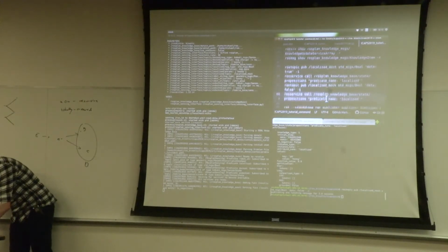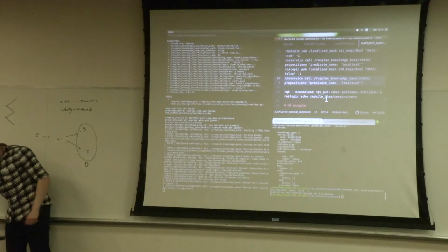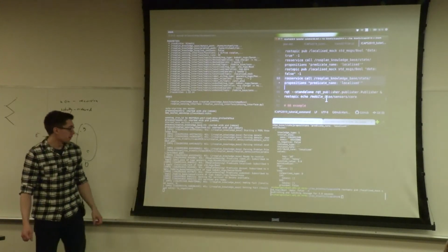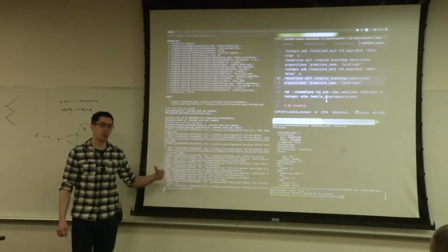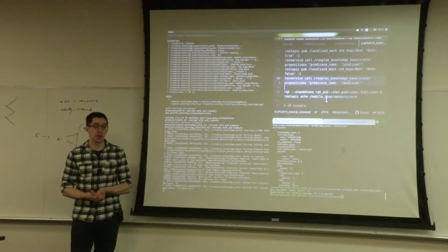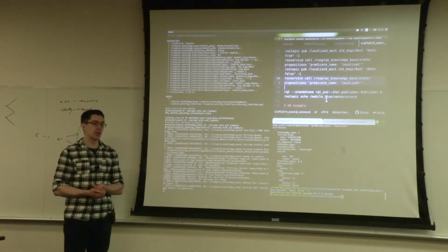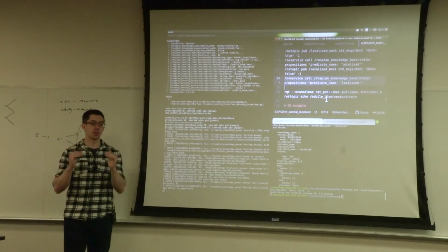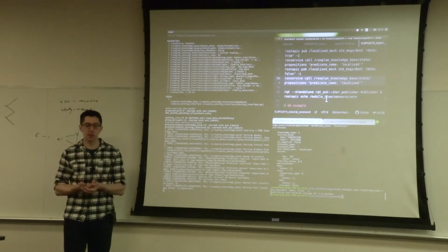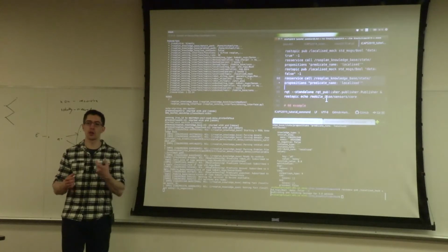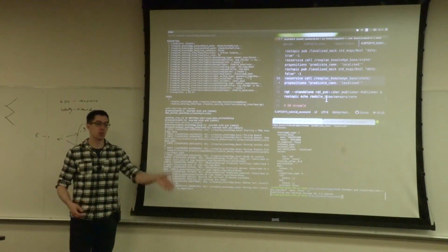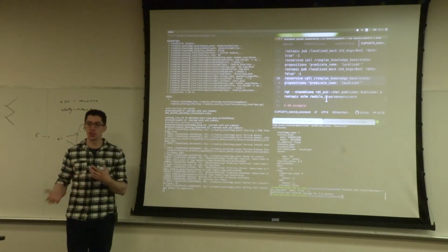But in that case, the unknown is there's no fact there. And when you generate your problem file, it's a form of PDDL for contingent planning. The initial state will include propositions which are true. It'll also include propositions which are false with the not tag, and some other constraint formulas such as one of these must be true. So it might say one of robot at waypoint 0, waypoint 1, waypoint 2, waypoint 3, waypoint 4. We know it's somewhere and only one place.